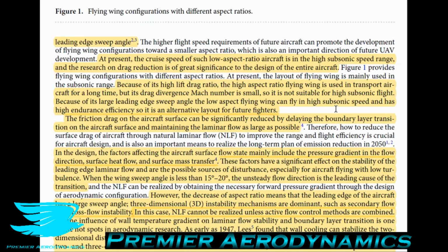The flow over a 747, for example, is laminar to a certain extent. Even though the Reynolds number is 10 million or more, whereas if you were to come down at sea level and have a 10 million Reynolds number, you can always be certain that the flow over any streamlined object will be turbulent.